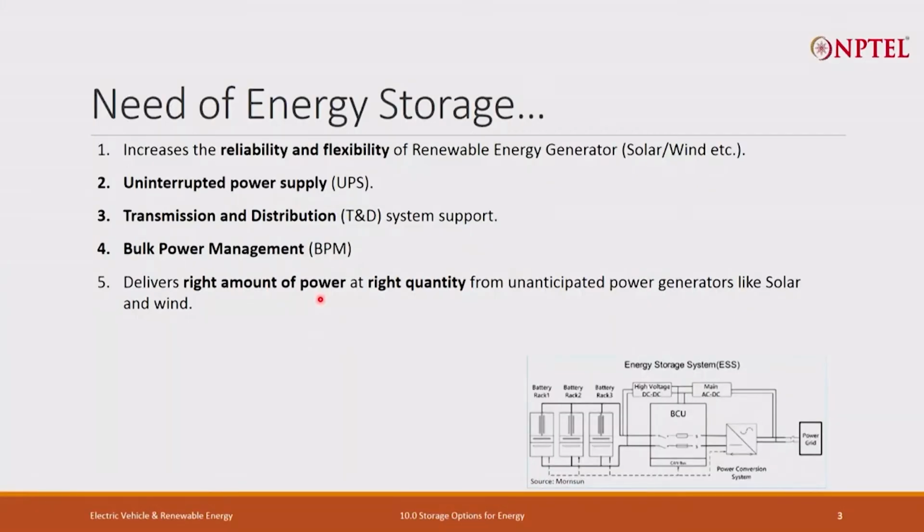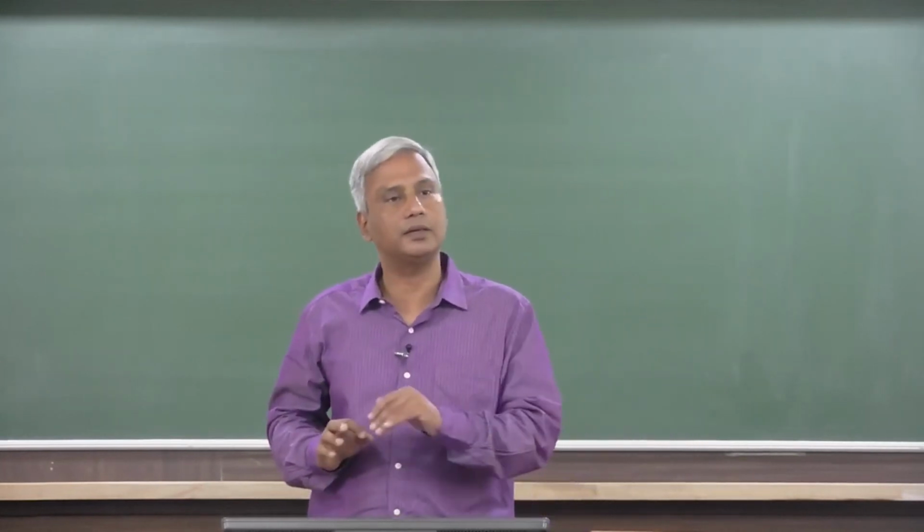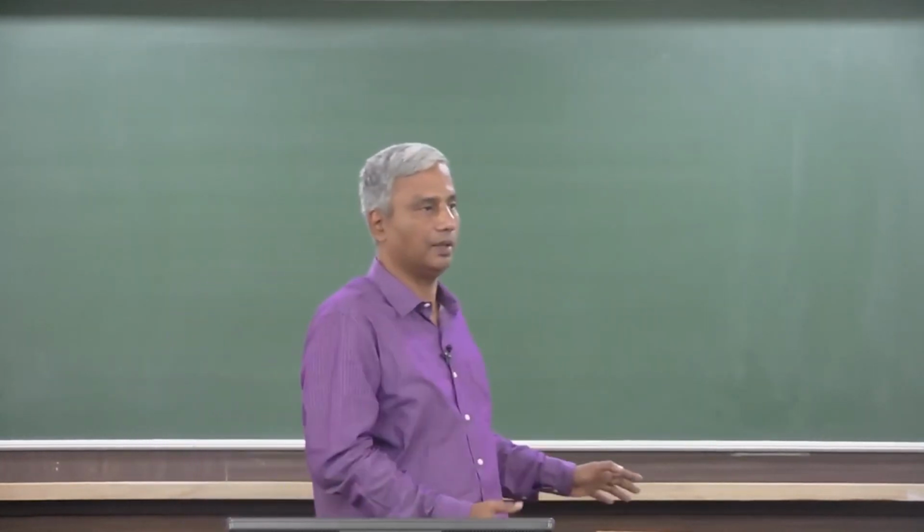Another important factor, or need, for energy storage is to deliver the right amount of power at the right quantity, and that's very important because renewable energy keeps fluctuating the whole day, and your demand also keeps fluctuating. You don't know if it's in the same direction or in the opposite direction. In such cases, energy storage gives you an option: you give only how much they need, and the right quality. If it is at 50 hertz AC, then it has to be at 50 hertz. It won't be allowed to go to 55 hertz or 45 hertz. It keeps on supplying extra energy at 50 hertz because of its storage capacity.